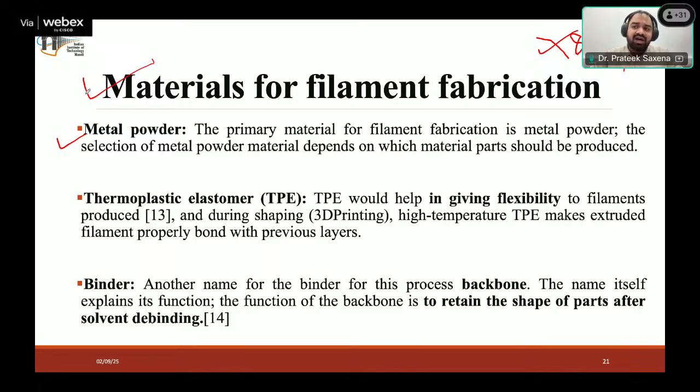You cannot use a cheap, low power laser source for 3D printing of copper, because copper is a highly reflective material. It is going to reflect back your laser beam, and your laser source will get burnt away very easily. There are specially designed laser powder bed fusion printers with which people have printed copper parts, but again it is expensive.